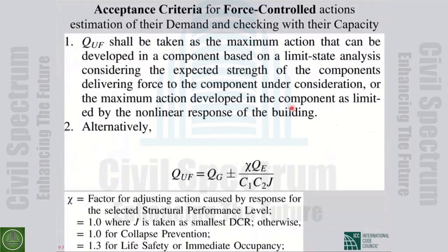So what was the problem with the deformation control actions, and how is it solved in the elastic linear analysis? The problem was that linear analysis cannot implement the damage in the deformation control elements in the model because it's linear.